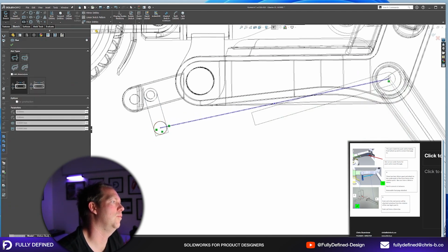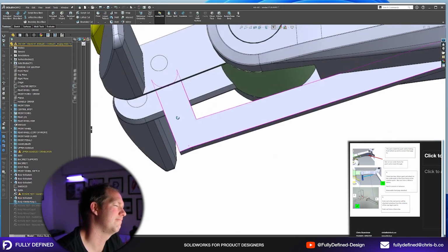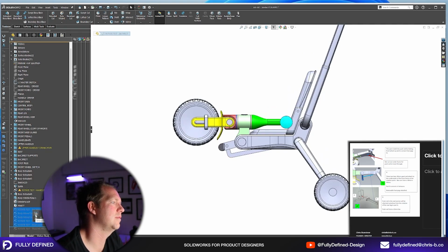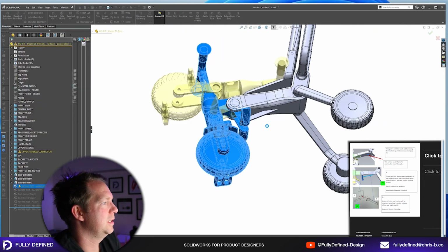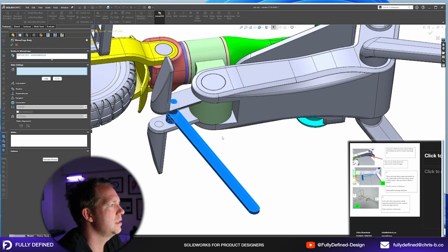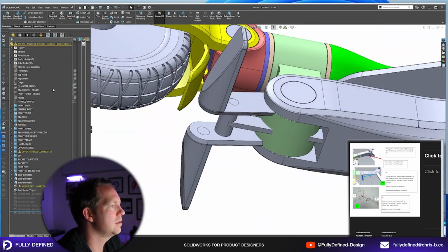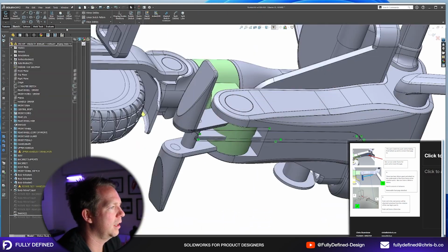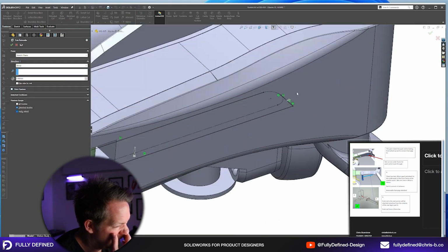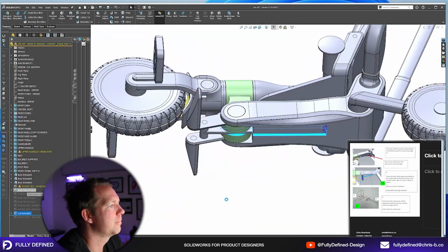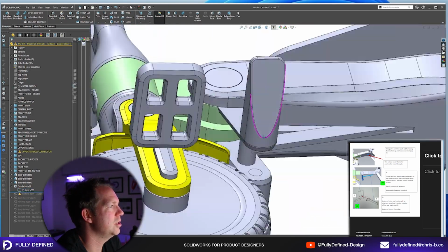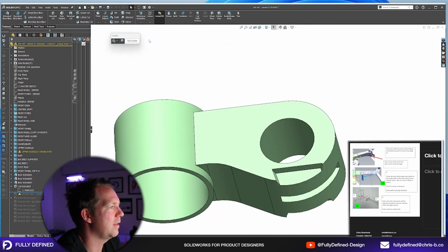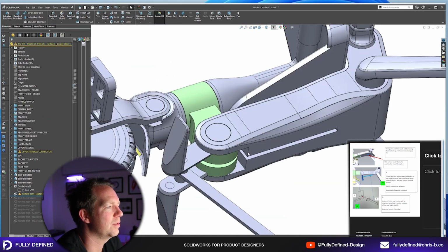It's not a downside, I guess, of the master sketch. Like the master sketch enables me to control the size of these parts. So I can actually fold it and I can go back to the master sketch while it's in its folded state. Without rolling back, I can just click on the master sketch, edit dimensions, and it will lower the height of the handlebars so that they're no longer interfering with the rear seat.